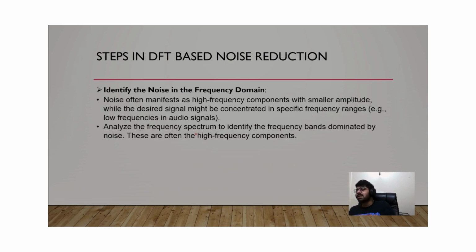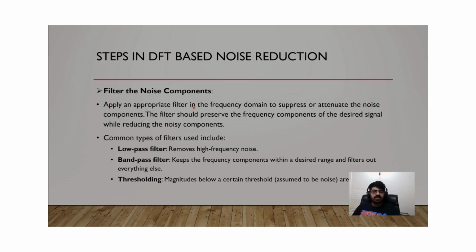Then our second step, we identify the noise in the frequency domain. We look at the frequency domain which we have obtained and mainly try to characterize the noise as high frequency noise. Noise is generally present as high frequency components with small magnitudes, whereas our desired signal might be concentrated in specific frequency ranges. We analyze this frequency spectrum and identify the frequency bands dominated by noise, which are often the high frequency components.